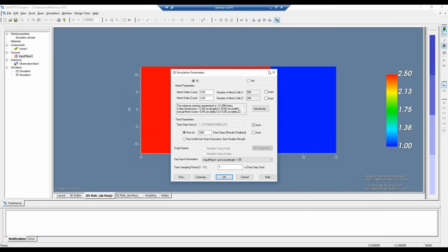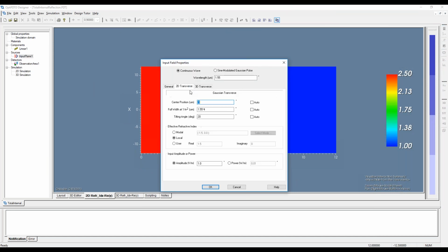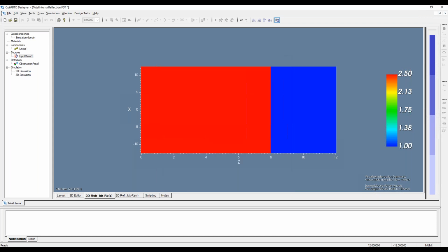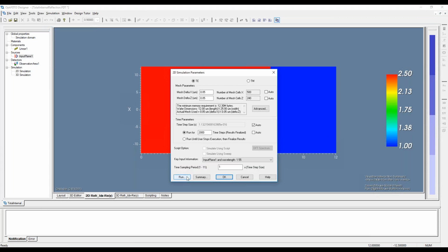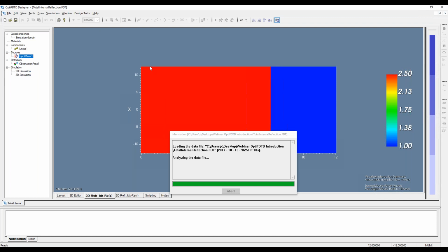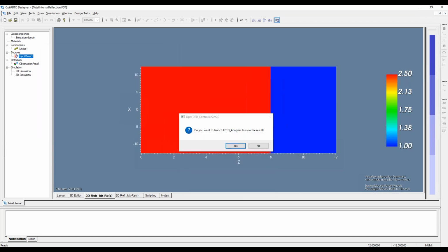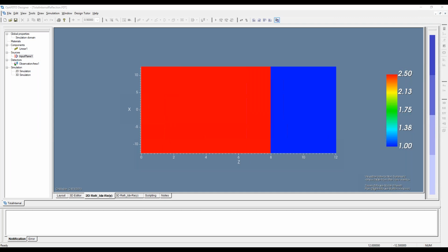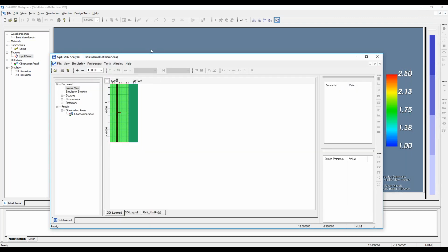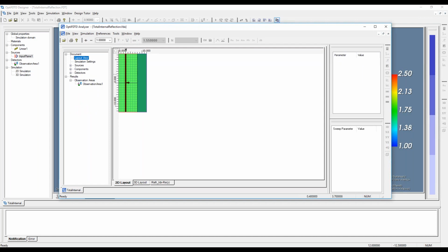And now I'll quickly, running out of time here, but I'll quickly see if I can change this to more of a critical behavior. This is the tilting angle here. You start thinking about good questions you might have. The reason we show a lot of 2D simulations live in these webinars is that they can run quite quickly. The 3D simulations easily can take a couple minutes if they're of medium size. And once you try and get into doing a convergence analysis, it can take hours and even days.